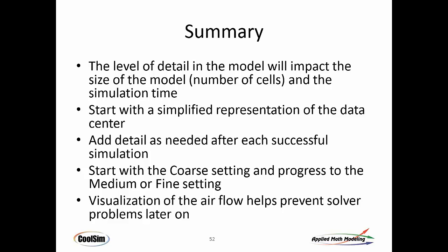Now, for the pathline plot we use an algorithm, and sometimes you don't see flow coming out of an outlet because the mesh isn't fine enough to show it. We do use an algorithm for how many pathlines we need per cell, and it's tough to come up with a common approach, a common way to have enough but not too many, because some of these output files can get very large with respect to pathlines because we're putting arrows on them.